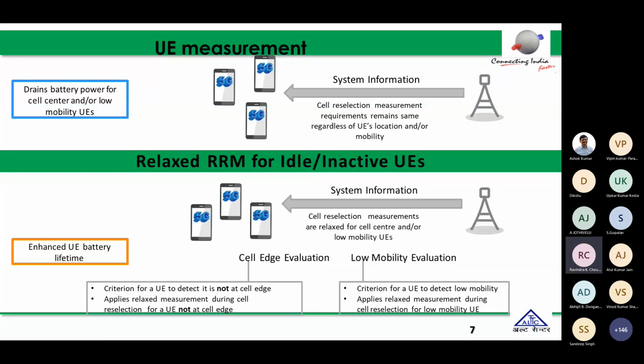Yes, please. Sir, in this measurement reporting by the UE, can there be an option for the network to page for the location of the UE and then accordingly ask it to change the cell or carrier? Like, sir, in 2G there were two methods in which the UE was telling I am here, and location and other measurements were conveyed to the BTS. But at the same time, there was a provision where the BTS, or say eNodeB, would page the UE to check whether you are still there or have moved somewhere else. Does that kind of provision exist in 5G?